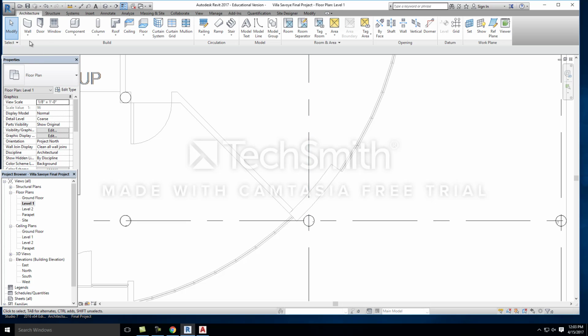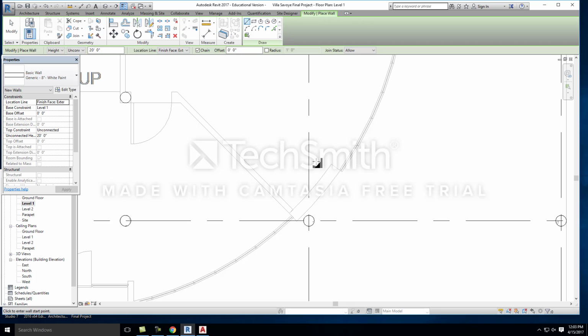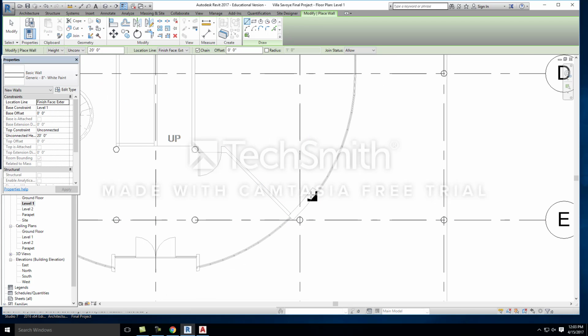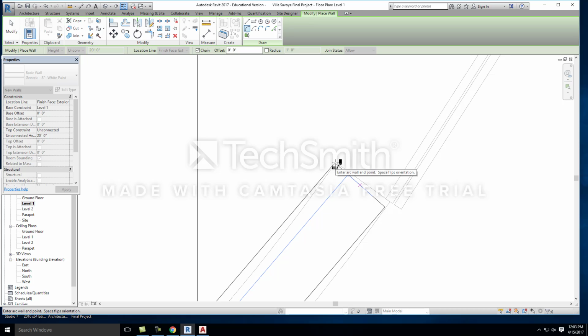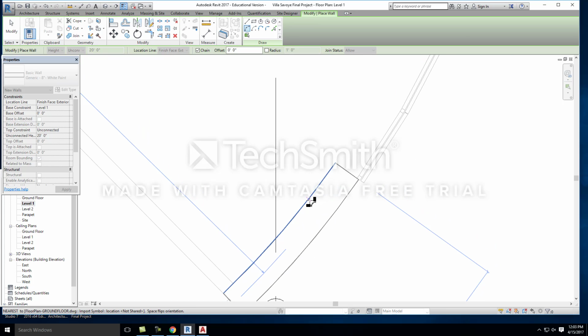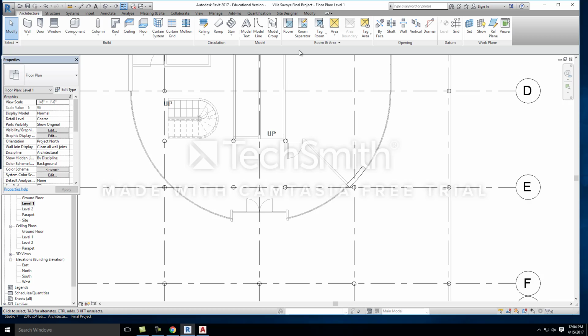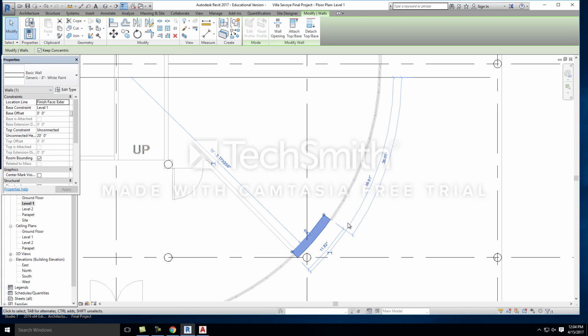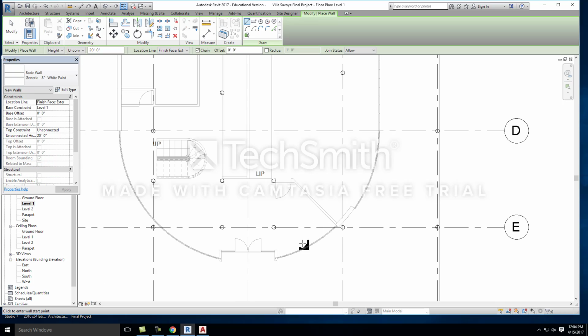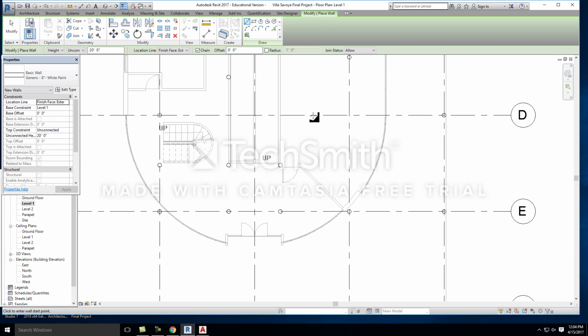So we can do this a couple different ways. Let's go back to our original white paint wall assembly, which I think will end up changing to green here in a little bit. But we can do this a couple ways. I can either go to my arc, okay, and I can click on the corner like so. Click on each of the 2 corners and actually recreate that arc like so. You can also use the pick line tool and pick the interior face of that wall. Okay. The nice thing about that option is that we can actually continue it all the way around.